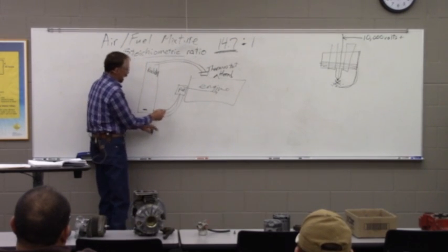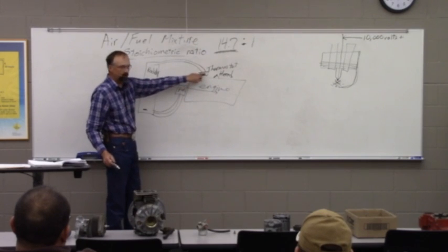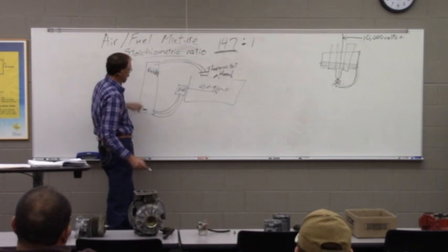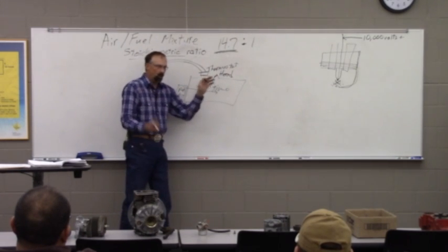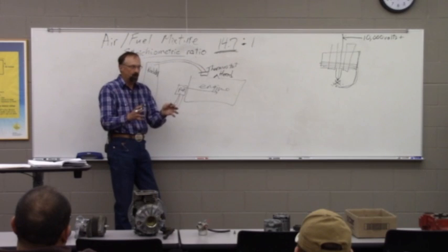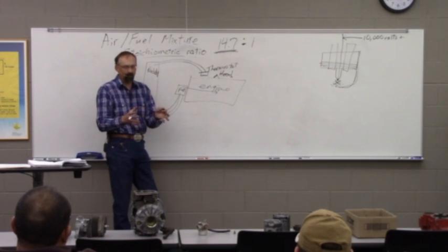Now, when this valve is closed, there's not going to be much flow from the radiator into the engine, because there again, our whole combustion process works much better with some temperature. Typically that whole combustion process does not work well below about 170 degrees.